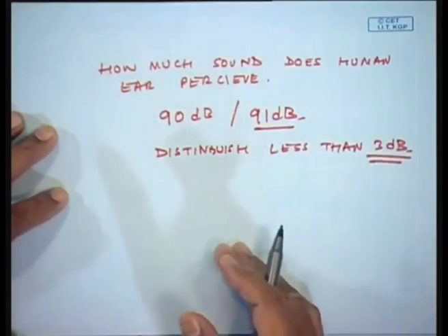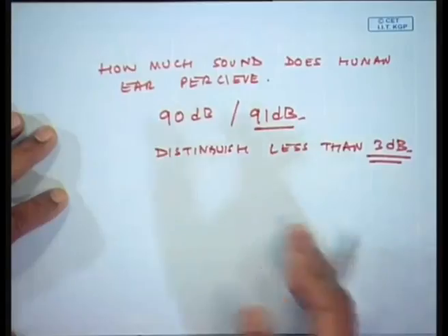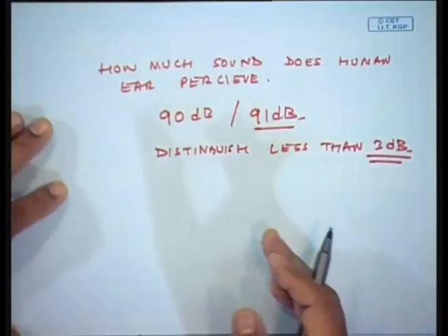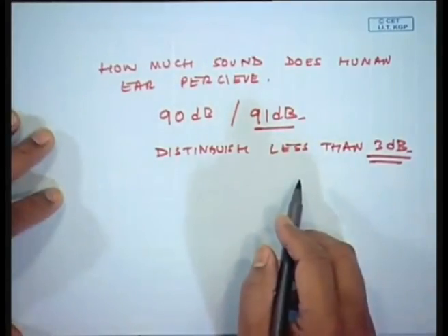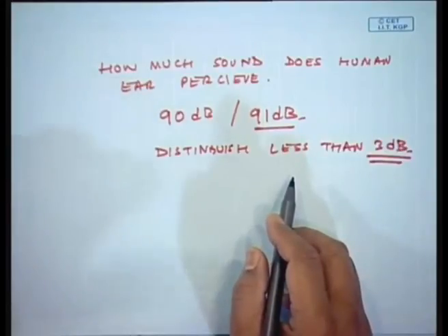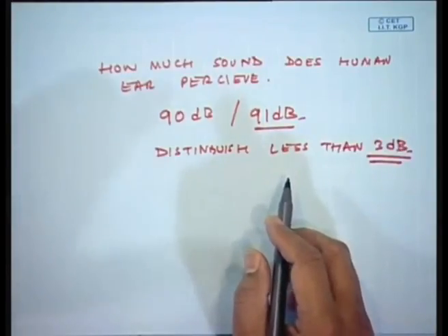You would have done a noise control and brought down the level from 92 to 90 decibels, you will not perceive it. Okay. To make a significant difference, it has to be more than 5 decibels. Okay. So, when we talk about alarms, sometimes a mere difference of 2-3 decibels will not be noticed by a human ear. Okay. So, we have to keep that in mind. So, sometimes during noise monitoring there are machineries or online analyzers which will tell you the exact sound pressure level. So, sometimes numbers may guide us to give us a better feel of the machine's condition.